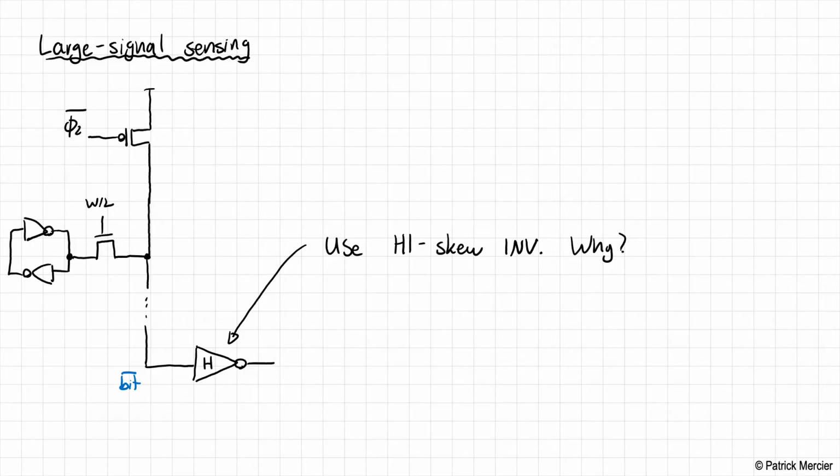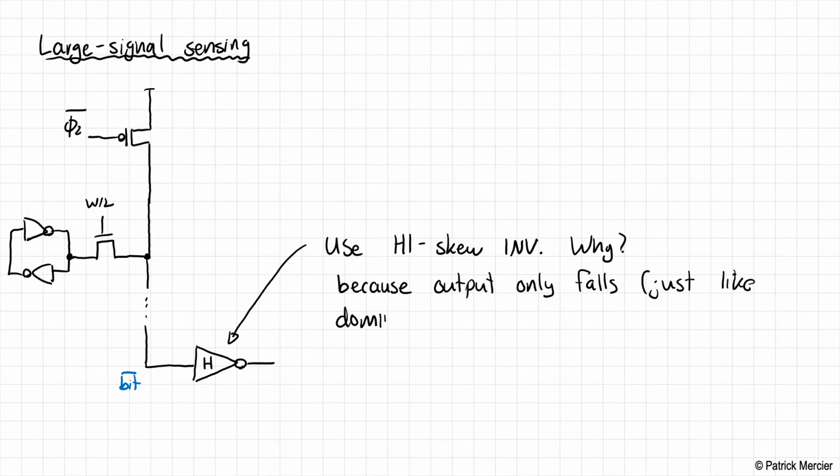Well, the reason is because the output only falls, just like domino logic, right? So we pre-charge the output.